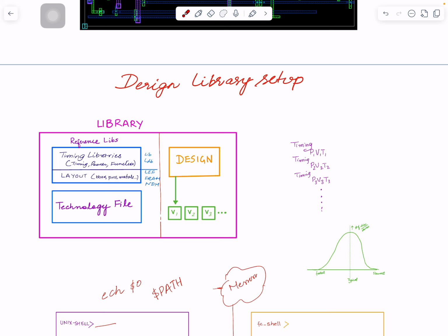Later on we will replace this higher abstraction kind of LEF frame or NDM with something very detailed. But right now in physical design, our lowest level is the standard cell, and below the standard cell we don't worry too much. We don't want to load very heavy data there. We are playing with standard cells. Our Lego pieces that we're going to build a design with, the basics, the lowest level in those is a standard cell: NAND, inverter, buffer, flip-flop, latches, and all that.